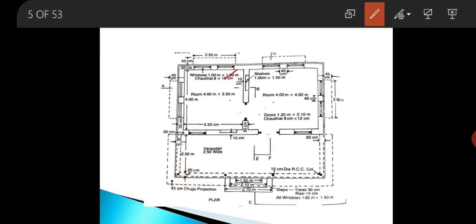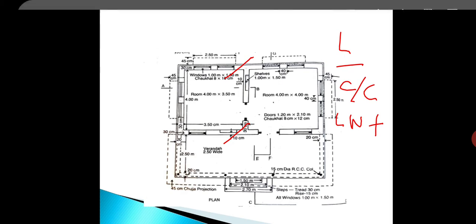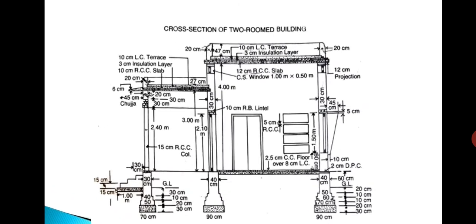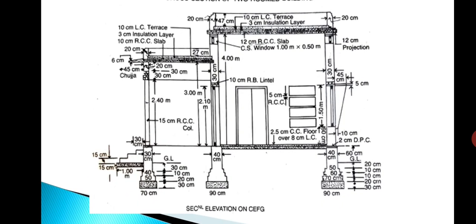So these two are the long wall of the room. So in order to get the length of the cement concrete work along this long wall, with the center to center length of this long wall, we have to add width of the foundation, cement concrete work in foundation on both the side. So now we will move to the cross sectional diagram of 30 centimeter wall.